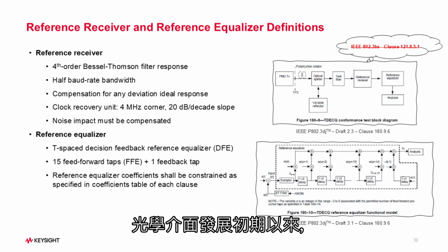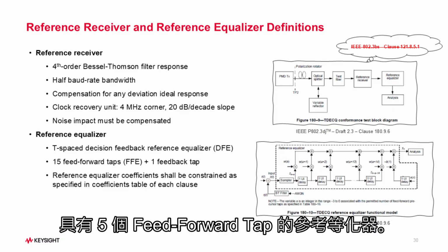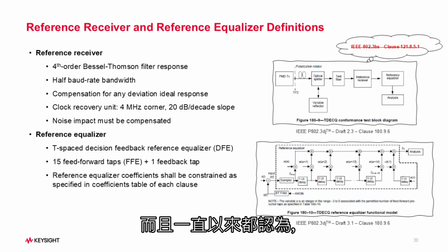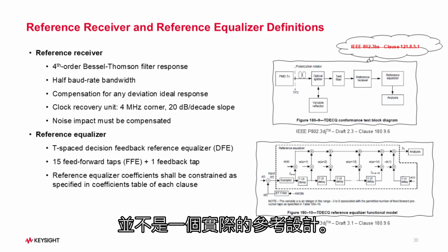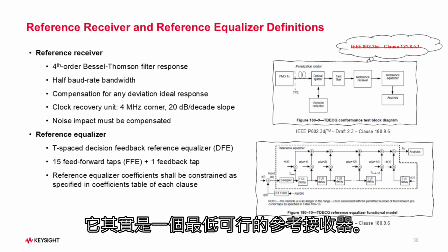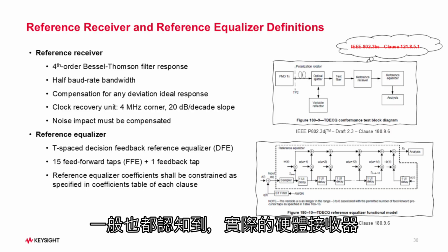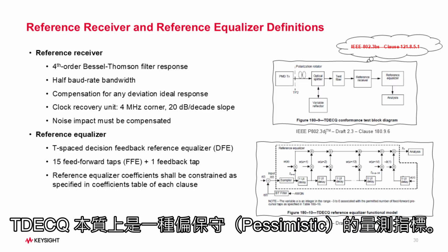optical interfaces, we have relied on 5 feed-forward taps as a reference equalizer. And it's always been maintained that the optical reference receiver is not meant to be a reference design. It's actually a minimum viable reference receiver. It is understood that the actual hardware receiver will outperform the reference receiver. And so this is why TDECQ is pessimistic in nature.